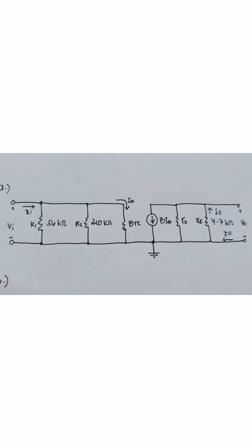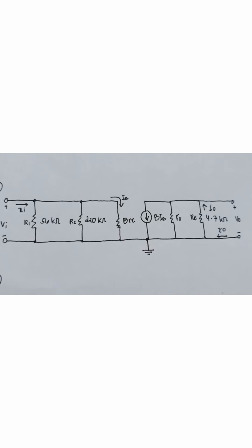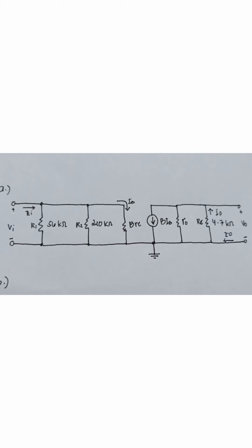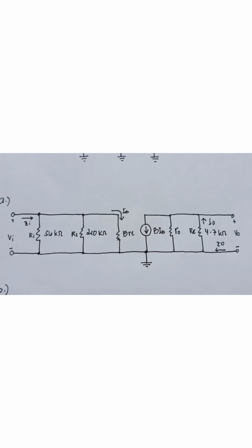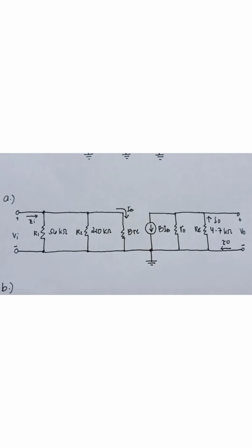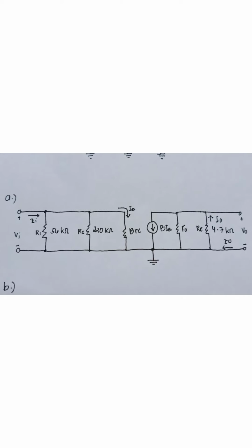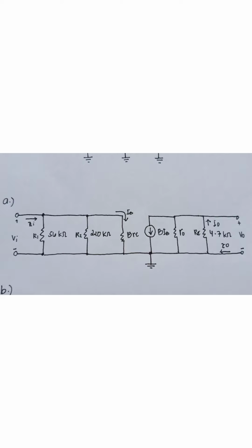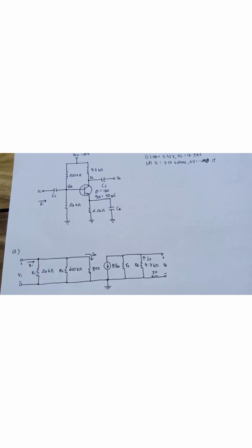Small signal model is an AC equivalent circuit. The nonlinear circuit elements are replaced by linear elements. Assume that all DC sources are turned off. Remove all blocking capacitors and replace with short circuits. Redraw the given circuit diagram into the small signal model. As we can see, the given circuit diagram is transformed into linear, or arranged in a straight line.